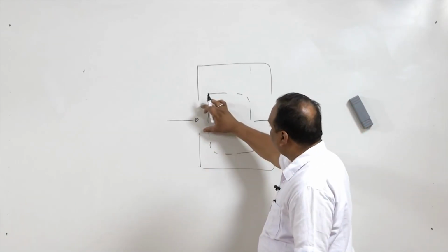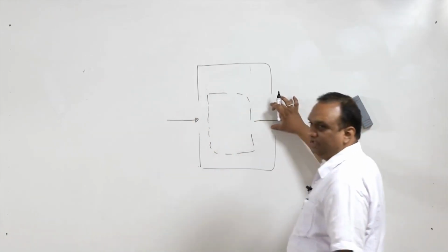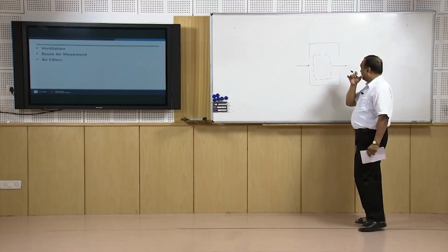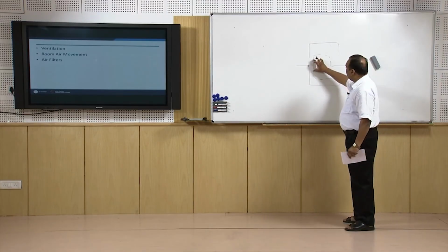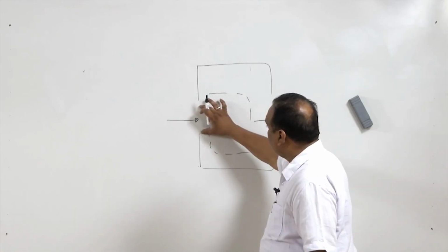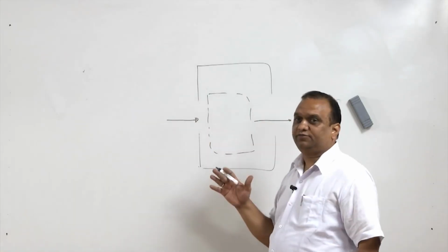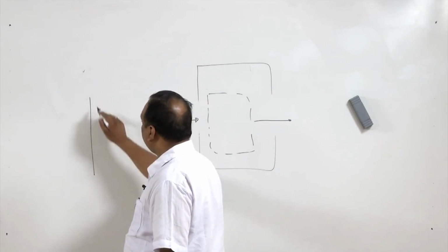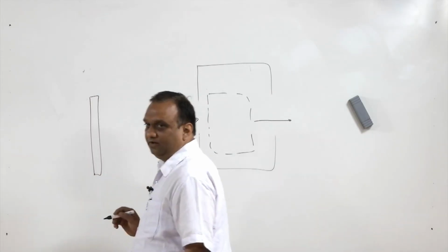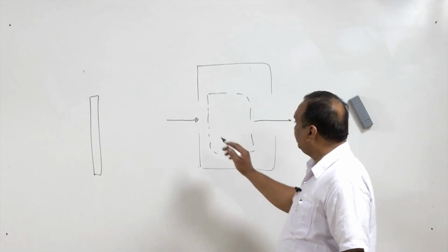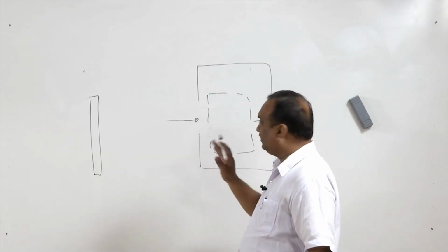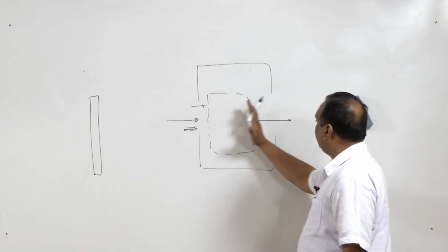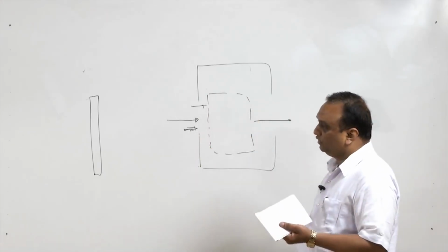It is something like a piston is moving in this direction and displacing the air. That is the ideal case, but it does not happen in actual practice. But most of the air is displaced, 90% or 80% of the air is displaced, and there are displacement ventilation devices available in market. If the air is coming to the room through these devices, there is a parallel flow stream, and providing a pistonic effect, it displaces air inside the room.